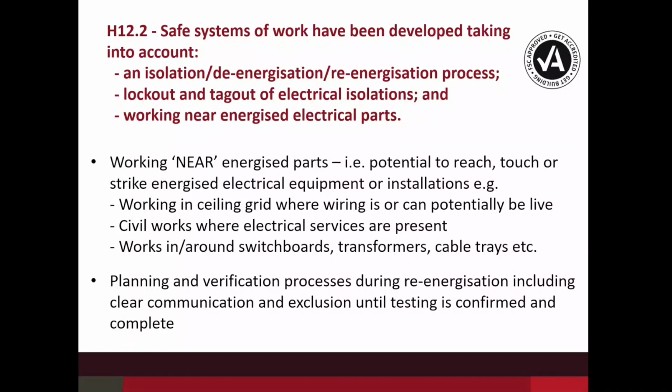One of the things that we did want to talk about as well is the re-energization. Planning for the re-energization is critical in terms of when we are turning circuits back on. We want to know that the process is in a planned state, so that it's not just essentially, we've done all of our tests and we're turning it all on. We want to make sure that the validation of that process is in a controlled fashion so that we know which parts are now turned on, that there's a communication that these parts are now energized and live and have the potential to be dangerous. And then we go into the other part, which is exclusion zones, until we get to a point where we're confirming that everything's okay and it's safe to move forward with other control measures.